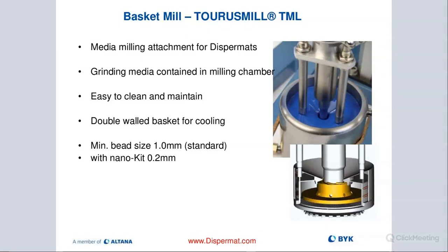As you can see here, we actually have cooling lines that go through our milling chamber wall. And that is very important, that we're cooling right there, because this is where we're going to put in all the energy, and that's where you're going to have the biggest problem with increased heat. So this is where we need to cool.